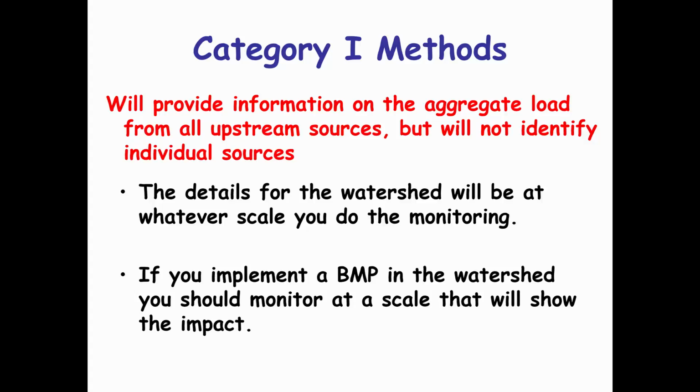And if you implement a BMP in a watershed, you should try to monitor, and you want to evaluate whether or not that BMP is effective at what it's supposed to do. Then you need to monitor that BMP at the scale that's associated with that BMP. If you put one BMP, let's say a saturated buffer, inside of a 5 square mile watershed, there's very good likelihood you will not see the benefit of that particular BMP just because of the differences in scale between the area represented by the BMP and the area represented by the watershed.